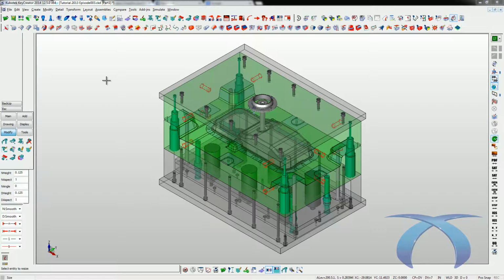So the first thing we want to do is start using the modify button, and we have a modify button right here under the modify pane. This is the most common button you will use in XMD for modifying sizes and the way components interact with XMD. Size would probably be the most common thing you'd use, but you also can modify things such as the units the product is in, whether it's a metric or an imperial component, or the way the component interacts with the mold, so the direction of a component, so maybe your guide pins, you want to go from the core instead of your cavity, etc.